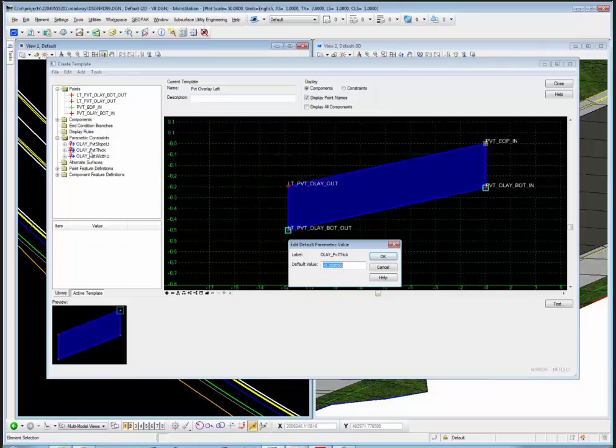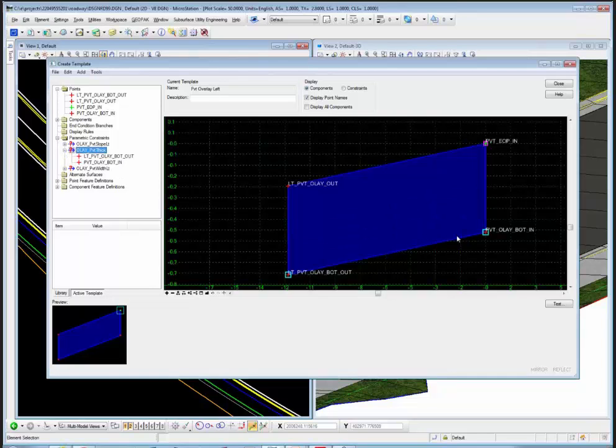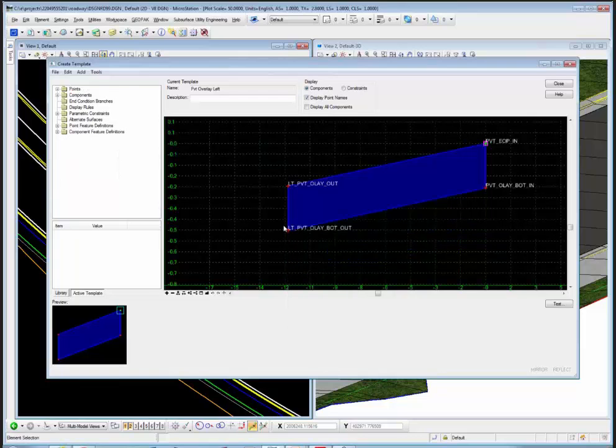And that way, if I go to what's called parametric constraint labels, all I have now is pavement thickness. If I want to change that depth at the same time, I would make sure it has the same label. So now I can set that minus 0.5, say, choose OK, and now both points change their constraints, not just one at a time. It's kind of silly to do that. You might as well just edit the points one at a time.